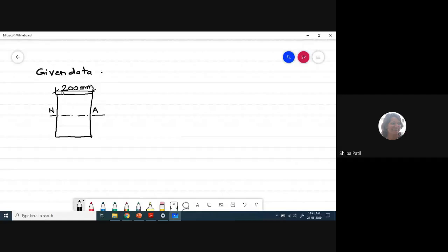For the effective depth, I have to show the reinforcing steel first in the tension zone. Let us consider the first case here, so I will simply write down, we will solve first A. As per the given data for the first case, how many bars are there? 2 bars of 20 mm diameter. So these are the 2 bars which I have drawn here. Let us fill them because it's a solid bar.